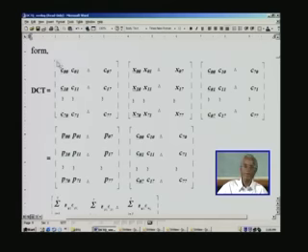So here the first matrix is C00, C01 and so on up to C07. This is the first row. Like this you have 8 rows, and the same is the case here, except that this row becomes a column here, and X stands for the actual image block. Each of them corresponds to 8 bits, because we are going to process only one color component at a time. We saw that only 8 bits, that is 1 byte, is required. So each of these will be 8 bytes of information.